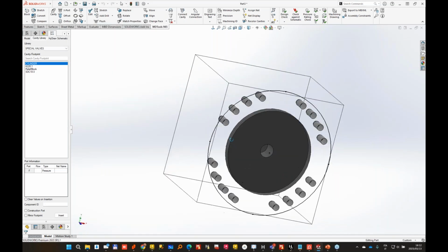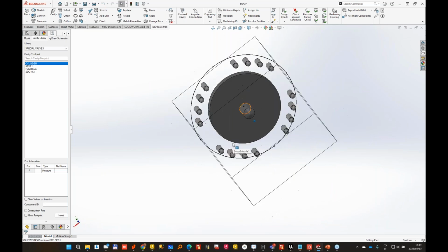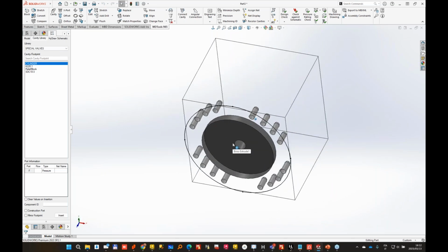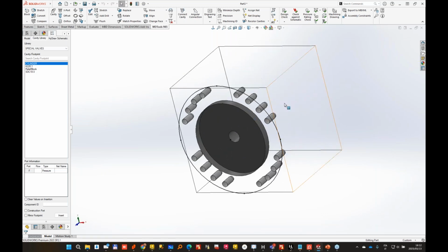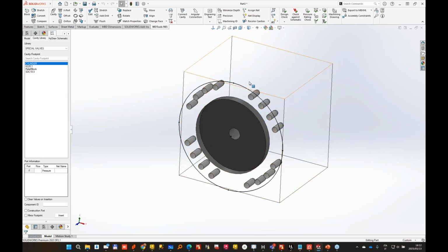And now that's my footprint made directly in the block. So by doing that, I was able to take a cavity that I had in another block and import it into my library for next usage. This is not the correct way this footprint must be assembled on the block, because I need an O-ring and I need through bolt holes.